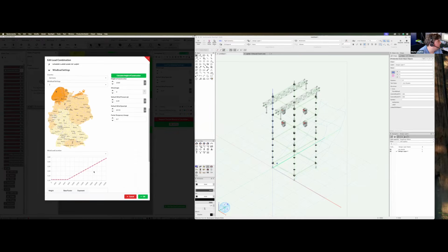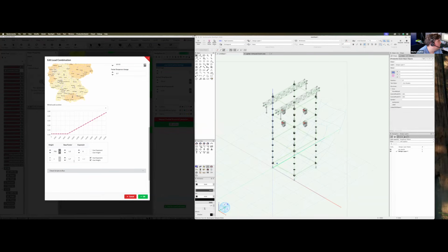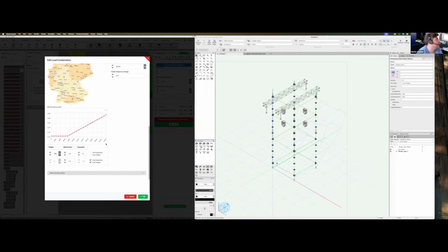So when you are outside in Germany, the Eurocodes apply. Up to 7 meters, the wind force gets a factor of 1.5. From there on, the factor is 1.7 and some other parts of this, and you see it's increasing every time. For example, at 24 meters, it is 0.6 in here. So Production Assist is smart enough to check every part of the truss, so how much wind force at this position point here is actually applied.